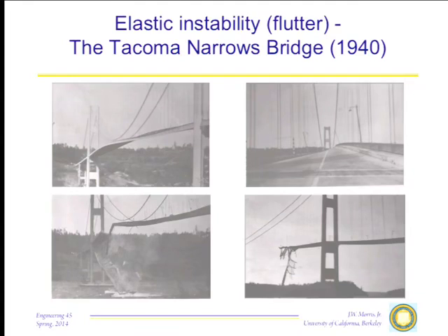vibrational analysis was enormously difficult, simply because most of the structures we have to worry about are not simple structures. If this bridge were in fact a simple beam, then even in the 1940s, they could have done a pretty good job of analyzing its harmonic vibration and designing around any problems. But look at it, it's not just a beam. You've got these columns sticking up, you've got the behavior of these cables, these wires, all these things interact. And the natural frequencies will be joint natural frequencies of all these different components. So while they could even in those days approximate the vibrations of a bridge from building simple models and analyzing those, it was really tough to get hold of the real models.